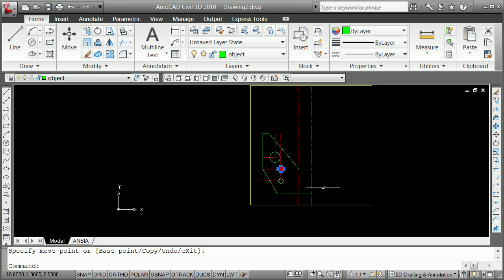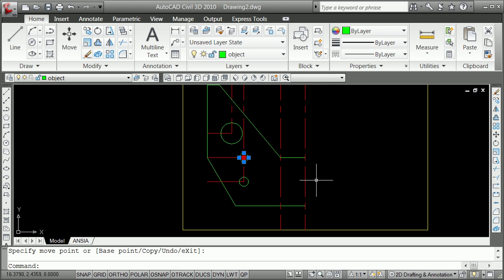You're now almost done, and in reality, because this hole here in the middle, you really don't want it to be 2 pieces. You might actually draft the whole piece, but what I'm going to do here is offset finally 1.125, offset 1.125, do it again, O offset 1.125, select object to offset, and that establishes the center line of that, and that is a diameter of 1.125.